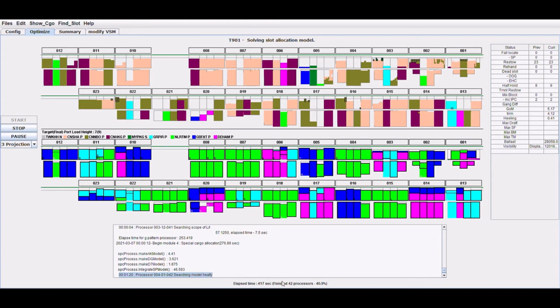When making the loading instruction, the container stowage rules such as the limit of stacking weight and height, and IMDG rules are reflected. In addition to these general stowage rules, there may be special loading schemes of individual companies or routes, for example, DG, Reefer, OOG loading restrictions, or 20 feet stacking schemes. These special loading rules are also reflected when creating the loading instruction.